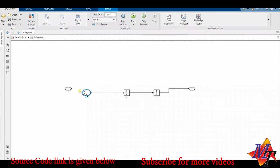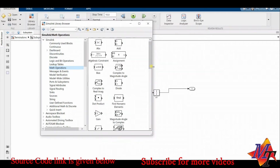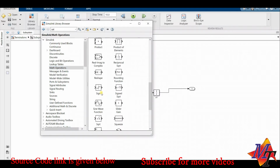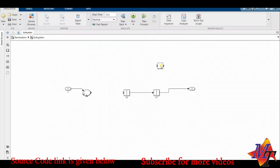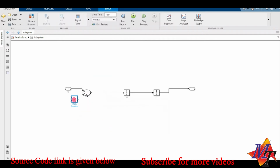Okay, so now we have this. Firstly u, then we have x2 cube. So for that we will need a power function here. For that we will take a math function. We'll double click it and set it as power.